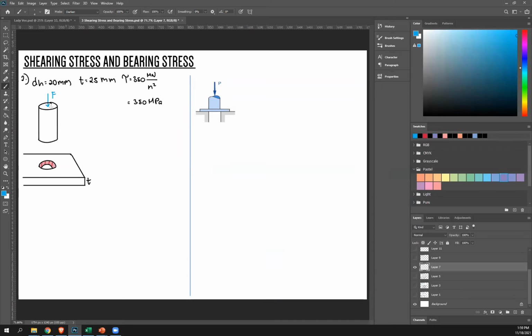Now upon analyzing this, if this is your shear force, remember whichever object is being cut, that is where your internal loads will appear. So your plate is being cut this way, so that is where your reaction will be, and the reaction is opposing the applied force. Therefore, the reaction is this way. There's only one area resisting that force, so that's just V. Therefore, we can say V equals F using summation of forces equals 0.